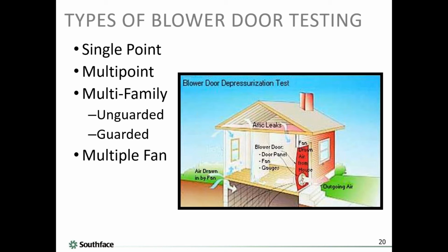A multi-point test is essentially where you test the building, get this, at multiple reference points. Oh, is that how you came up with that name? So a good example might be you would start at, say, 75, and then you would work your way down to 25. And at 5 pascal increments, you might take a measurement, and therefore you would have multiple reference points. Yep, and the advantage of this we'll see in a second is much greater accuracy and greater confidence in the